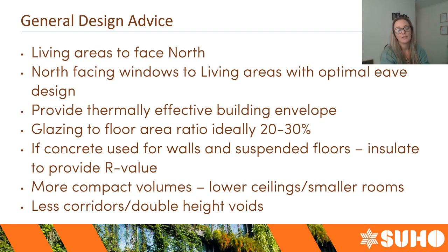But if you insulate it, it will be a more stable product for your dwelling, because it's slow to react to external environments, the heavy concrete walls and block walls, and insulating it actually controls the thermal properties of it better than just leaving it to its own devices.